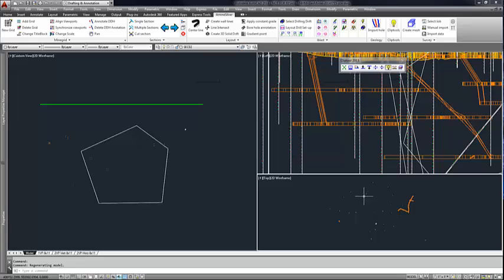There's a faster way. I can just go to this view and say set this view, and it says which view to set, this one, from which view to set. So I want to set it from this one. I want to see from here, pull my little elastic bands here, just pull it down so I can see this drift right here. So I'll do that again. So this is the view I want to set. I want to see from here down to here. You can see here's the drift that I've just set right here.